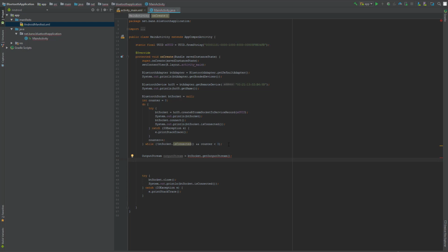And if you recall from the sketch that we made for the Arduino microcontroller, the value that our sketch is expecting to receive in order to launch the print sequence was ASCII code number 48, which is the ASCII code for character 0.